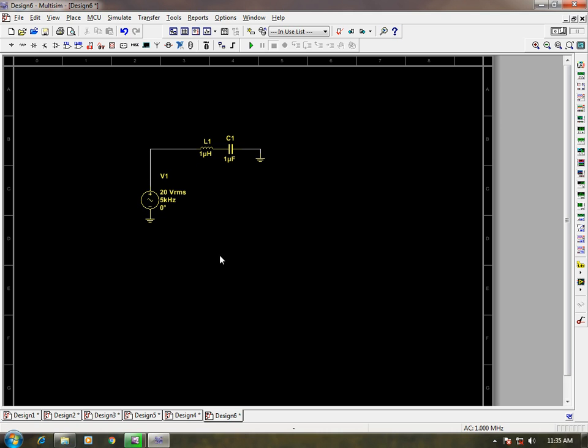If we increase the resistance of a simple circuit, the curve gets flattened, and consequently the spreading of this curve, the bandwidth, gets increased, and hence adjacent channel interference gets more and more into the circuit. So it is not a desirable case.